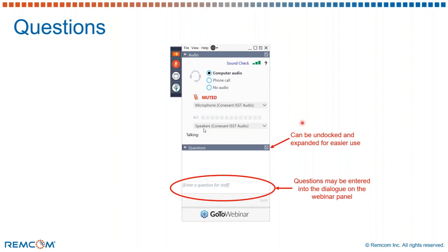So how are the codebook values calculated? The codebook values can be calculated from one of the features that we have, which is the array optimization, with which you can provide the directions at which you would want to point the beam, and from that you can arrive at the different phases and amplitudes for the different ports, which in turn gives you the values for each of the entries on the codebook. Also, you can get these values empirically if available.